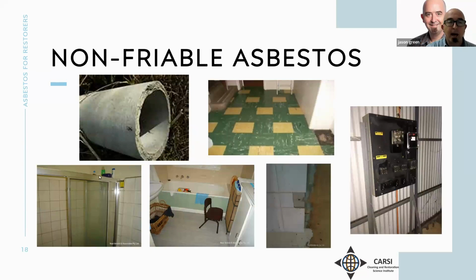So you can see here, asbestos fibre cement pipe work and guttering, things to do with roofing is very common that contain asbestos materials. Vinyl floor tiles. You can see here that the tiles are a bonded or non-friable material, but some people may miss what we see over here, which is the actual glue or the adhesive. Blackjack is what it's known as, and that can contain asbestos as well. So make sure that is tested if you're working in a building that may contain asbestos.